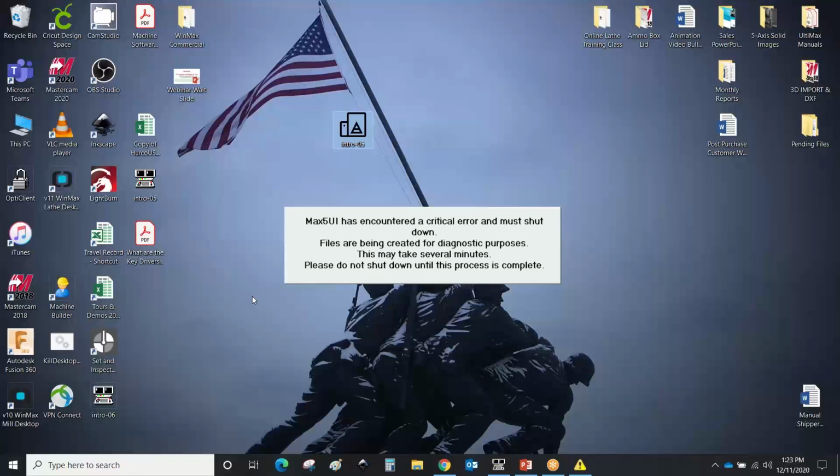So you would have to take that off to Mastercam or something and flip it, save it, and bring it back in. But at least you didn't have to draw the geometry and create everything. The control did that for you. Now, the only other thing that you have to be aware of is when you export your STL file from your CAM system.